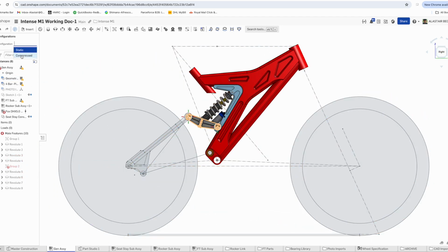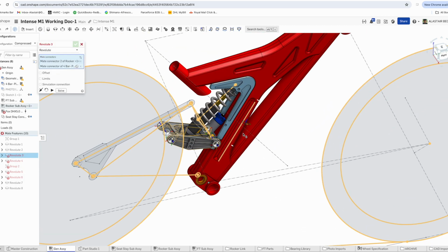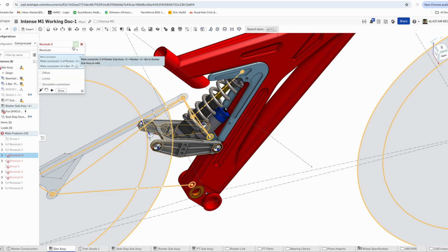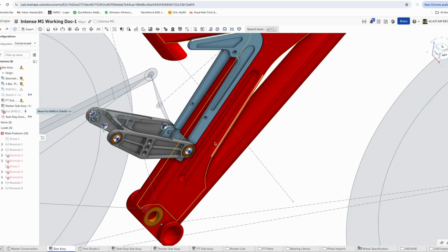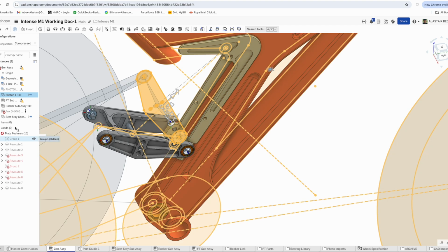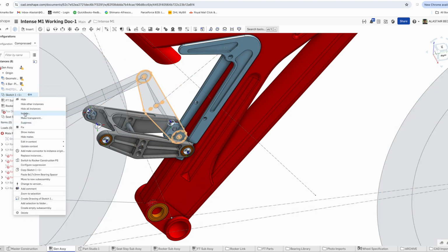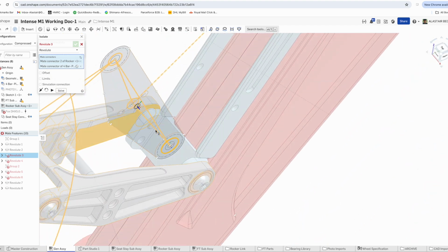We're creating a sketch, bringing that sketch in, and it almost acts as its own kind of three-dimensional solid part. So yeah, we're just checking that everything's working there. There was a glitch with the rocker link that I later found out what had gone wrong, so I'll redo it at some stage, but it was just to do with the sketches and the way the sketches were attached. So in-context modeling is not idiot proof either. It is possible to get muddled up and confused with it.